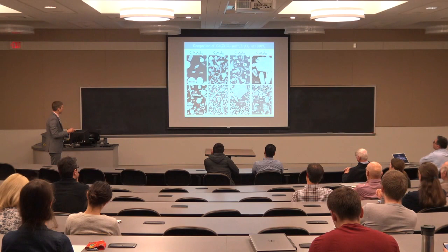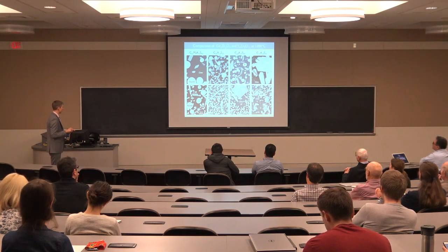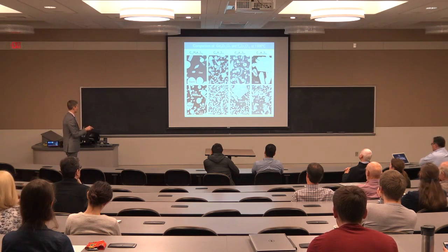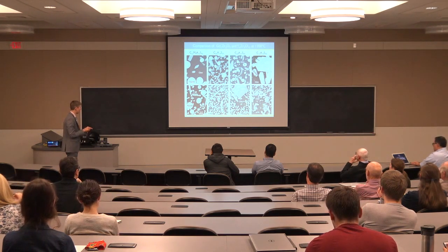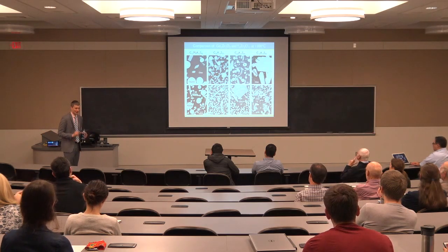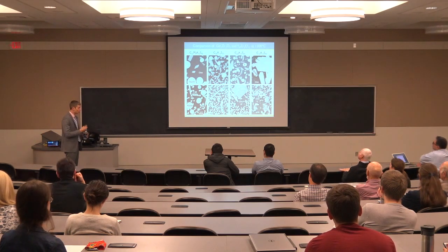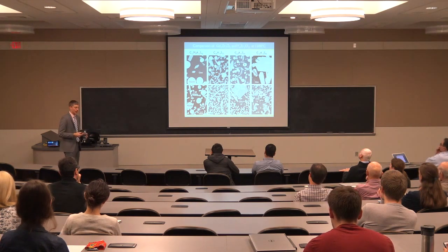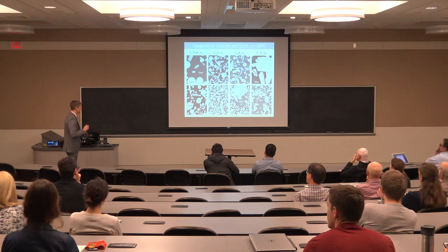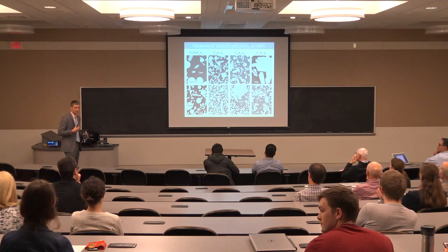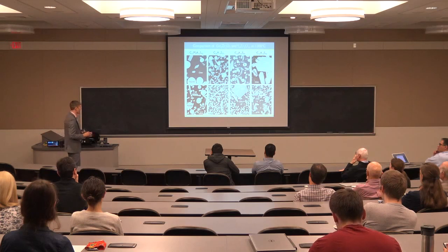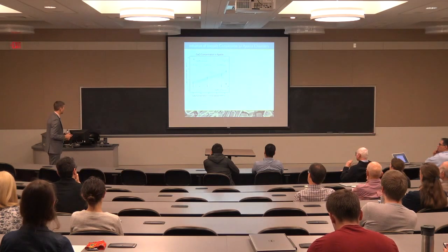If we do the same experiment now with gadolinium, the bottom row is gadolinium, we see first off that the morphologies have changed. In this case, they look pretty similar. We get apatite and fluoride in the glass. But in this case, we no longer see fluoride. It turns out that the zirconia precipitates instead of the crystal phase with almost no gadolinium in it. And that leads to a significant increase in the amount of apatite that we can form, because the gadolinia is going into the apatite phase instead of into the reprecipitated zirconia-based phase. And that's a good thing.